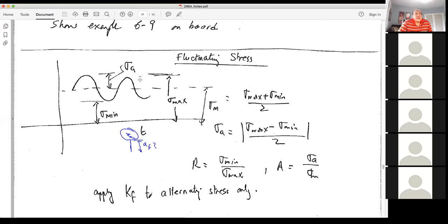If you have a stress cycle that has a mean value that is different from zero, the idea is that the fluctuating part causes damage by itself, which we know as fatigue, and the steady part, which is the mean value, causes another form of damage. Then we combine them together so that the total damage function does not exceed 100%.